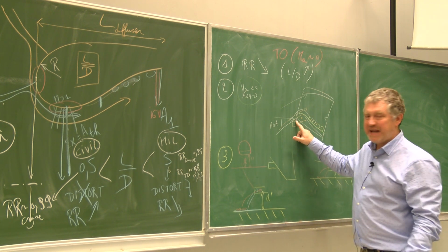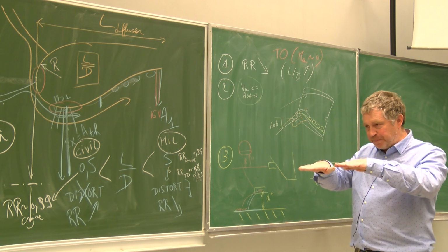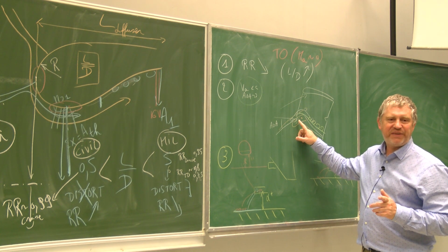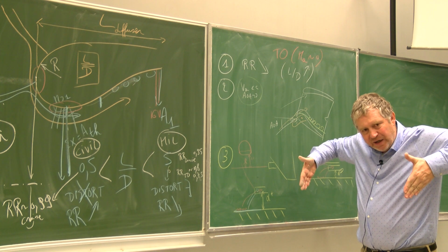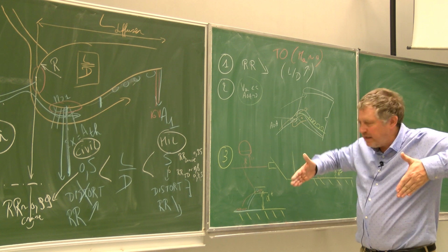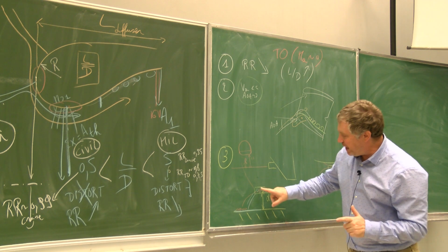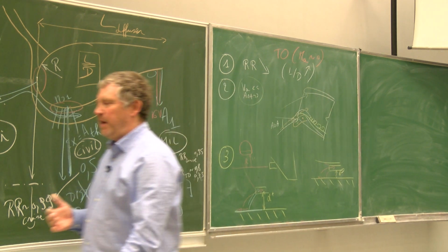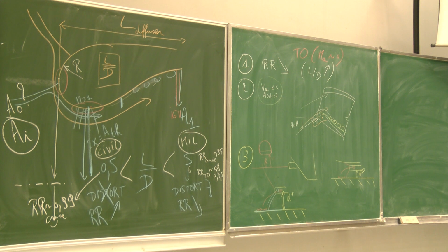This is, for example, like this on the Eurofighter. There are two small lips that are going down. This is also like this on the F-15. On the side intake, the side intake is going down like this when you are in this high angle of attack configuration. And related to this case, for example, you have some aircraft that are closing their intake.